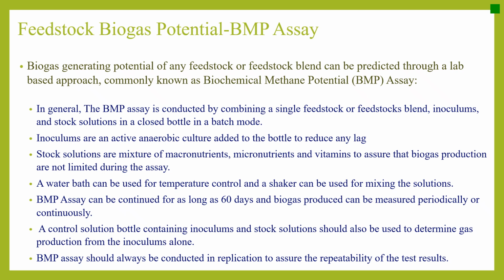Inoculum is an active anaerobic culture added to the bottle to reduce any lag time. Stock solution is a mixture of macronutrients, micronutrients, and vitamins to assure that biogas production is not limited during the assay. A water bath can be used for temperature control and a shaker can be used for mixing the solution.